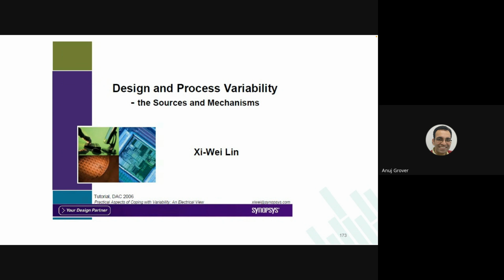You just put what happens if Na increases, what happens if Na reduces, and you will have the answer for yourself. Is it not? So the impact of these variations can actually be modeled based on where your device is placed. Stack effect, what is its impact? Can be modeled. So there are some kinds of variations which can be easily modeled. Those are referred to as systematic variations.